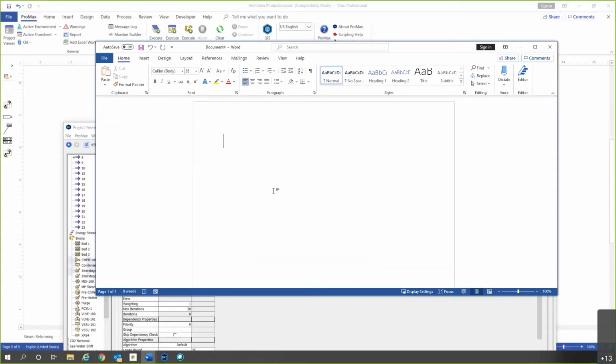The equation that we're trying to target is we want T outlet to equal 910 degrees Fahrenheit. How the solvers work is we want to solve this equation to 0. So to solve for 0, we'll simply subtract 910. So this part is what we're going to want to put into ProMax.